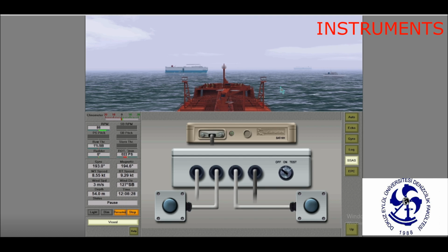In the control panel, the imitator of the Ship Security Alert System is intended for providing ship security alert and checking the system operating capability. To turn on the SSAS power supply, set the 3-position switch on the control junction box to the on or test position. The system responds by switching to the operating status, the process taking 2 minutes, during which the light indicator of the imitator on the Inmarsat D+ terminal reflects various internal checks and adjustments of the communication channel.